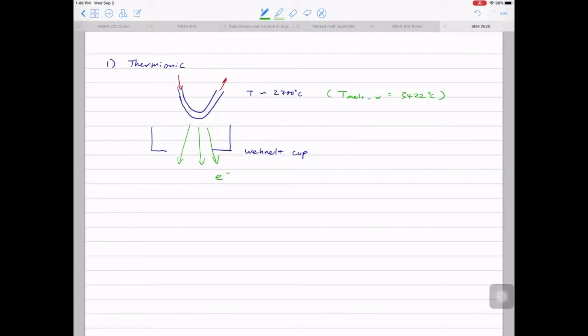Shouldn't it be at the sharpest bend? Compression side? Compression side is actually less likely to break. Materials in general are stronger in compression, weaker in tension. Some materials don't have the asymmetry, but if you have a crack, if you apply tensile stress, the crack can propagate. But if you apply compressive stress, the crack can be arrested.